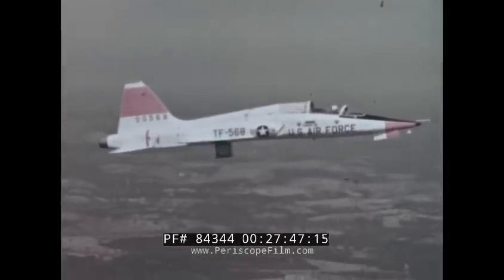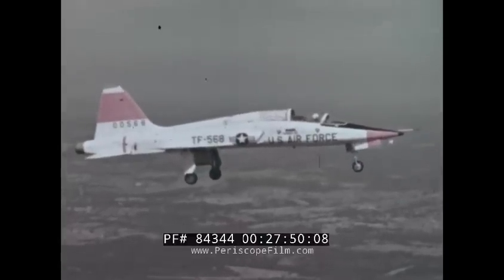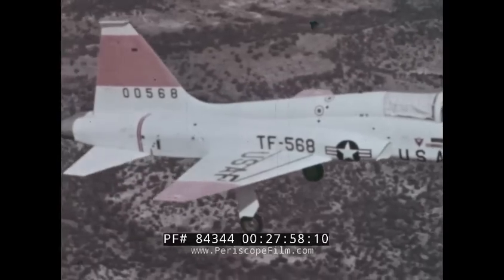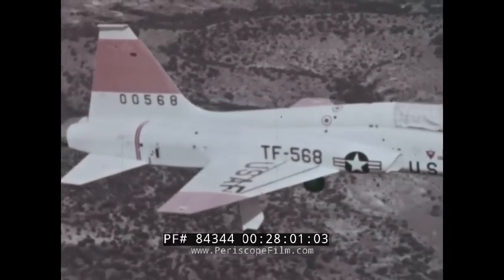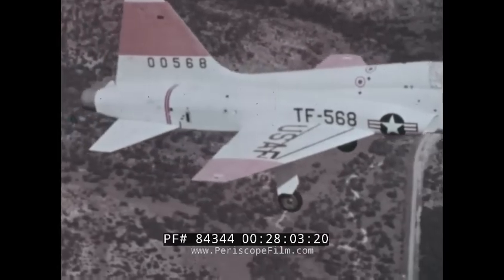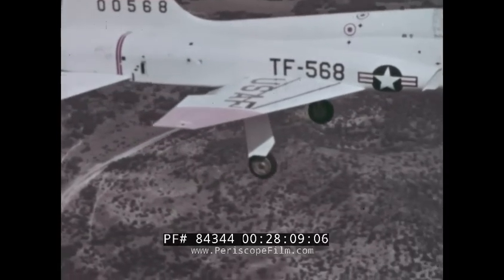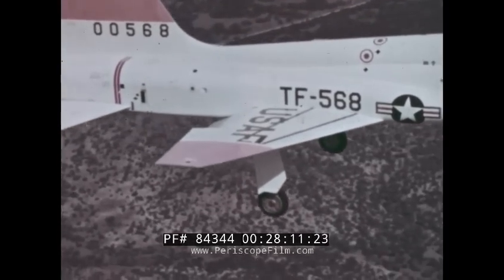On base leg, the airspeed will be 185 knots with this fuel load. Extend the gear. On final approach, lower 60% flaps and slow the aircraft to 155 knots. Normal selection will be used on final because it would be difficult to set in headings desired when using the bank steering bar. From here on, your configuration, airspeed, and procedures are the same as for ILS. Full flaps may be lowered when the runway is in sight.